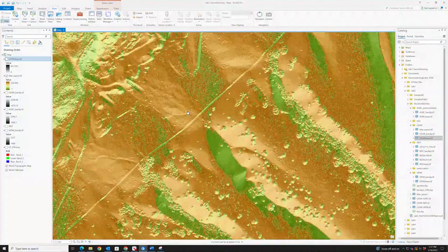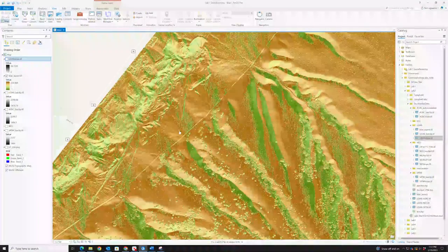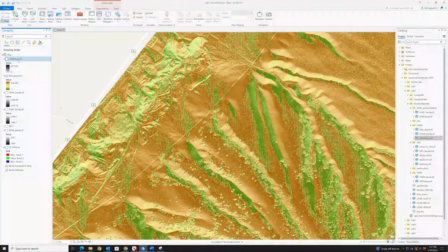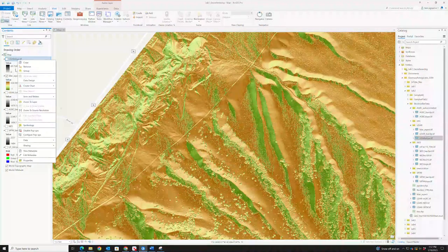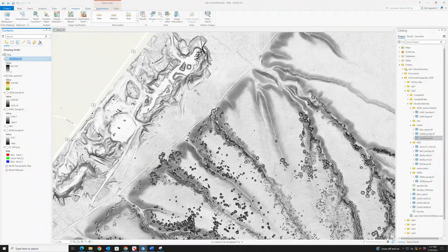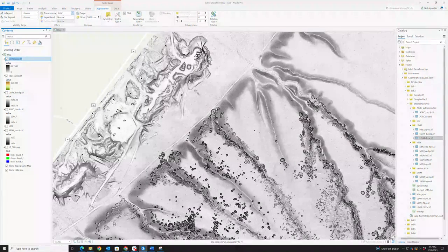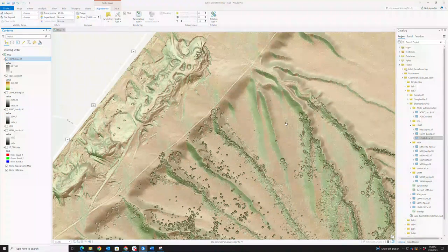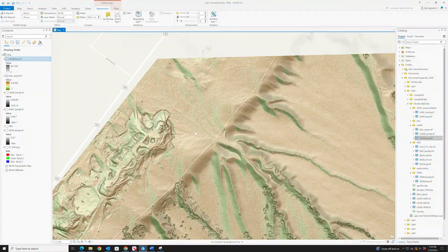And you can see some of the details of the alluvial fan in the aspect map. So what I like to do is actually make these kind of transparent over each other. To make an image transparent in ArcGIS Pro, we'd click on it, go to imagery, appearance, not imagery, and go to transparency. Whatever we're selected will become the transparency we tell it. So we make it 40% transparent. Then I can see the kind of details of the slope, and I can also see these alluvial fan piles going off in the distance.